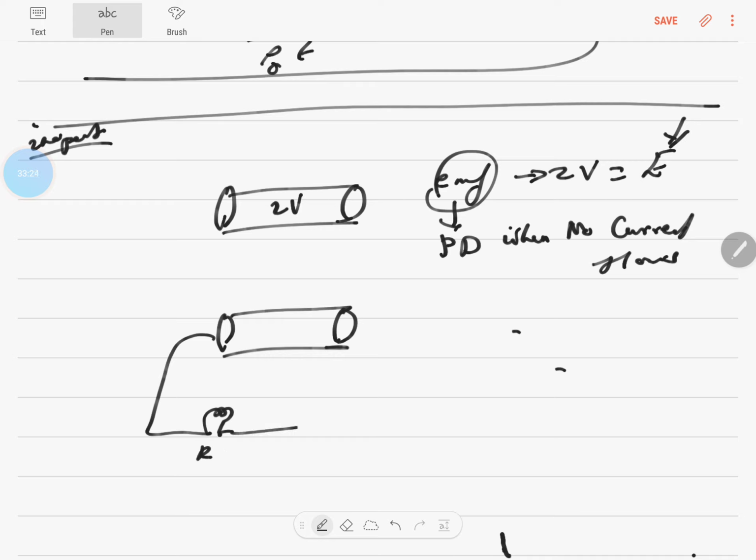That is an external resistor and a switch. Suppose you close the switch, the key is closed and current is allowed, and you connect a voltmeter in parallel and note the reading of the voltage. It will not show 2 volts, it will probably show 1.6 volts or 1.8 volts. So will you go back to the shopkeeper and say, I bought a 2-volt battery, it's showing only 1.5? You can't do that. Why?